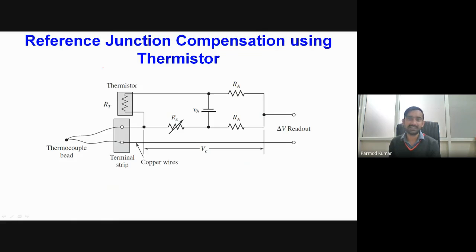That is not practically feasible, because every time we use a thermocouple, we would have to spend some additional cost on creating a reference point and then calibrating our system, and we would always have to maintain the temperature of the reference point at some fixed value.